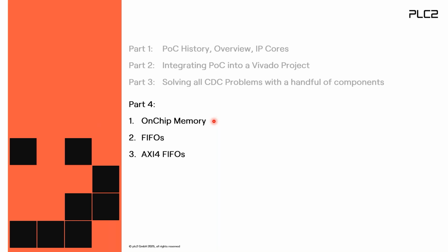When we have such an implementation of a memory layer, we can build other higher level features on top of it. One was having FIFOs implemented on top of simple dual port RAM, and based on FIFOs, we can have some FIFOs and buffers inside of our AXI4 network. This is my final conclusion for today, and I want to hand over to Anna for the final words.